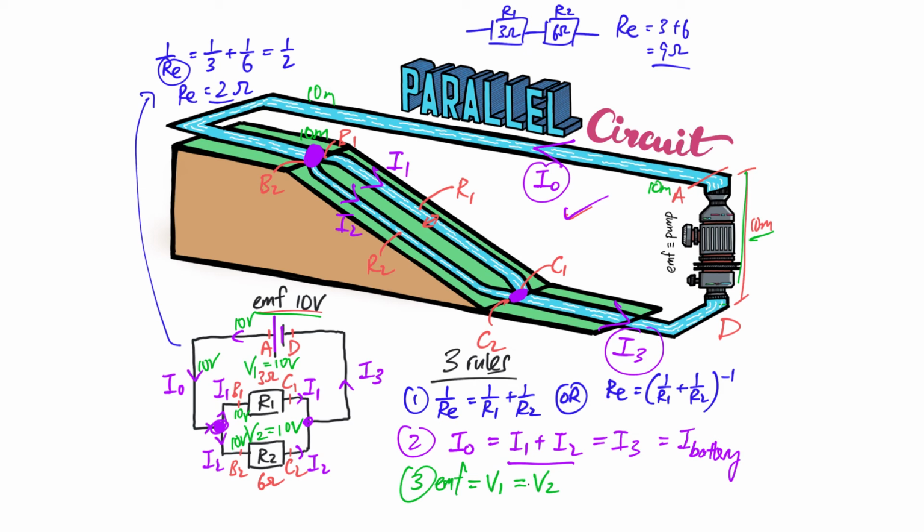On the other hand, here at the bottom from C to D, you can see is ground zero. So this will be 0 meters. On the circuit here, you can see that this is 0 volts, and even at C1 is 0 volts. C2 here will be 0 volts. So once again, if you find the voltage difference, 10 minus 0, that's why you say that there's a potential difference of 10 volts. And likewise for V1, you find 10 minus 0, the potential difference across this branch will be 10 volts.